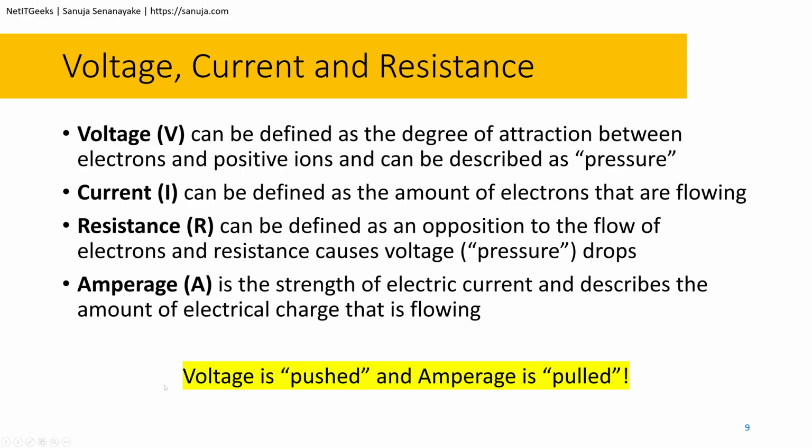So they're going to just send the 12 volts, because if the PoE device sends 24 volts, it's going to burn out the end device. So keep that in mind. Modern PoE devices actually are capable of negotiating the voltage they need and also the amperage they need. But again, the device will pull the amperage from the power source, but the voltage will be pushed. So it's very important that you don't plug devices that are lower voltage rated into a higher voltage power source, unless it has that smart capability of negotiating the voltage.